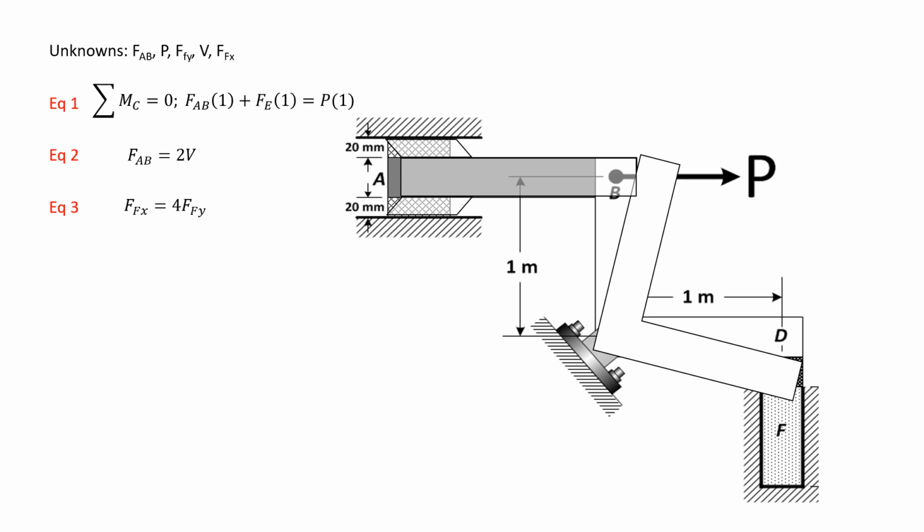So the point A will move by this much, and that would equate to the deformation of the rubber pads, the shear deformation of the rubber pads. And then AB, which is subjected to a tensile force, will elongate. Hence, the movement of point B will be the sum of the deformation of the rubber pads and the deformation of AB.